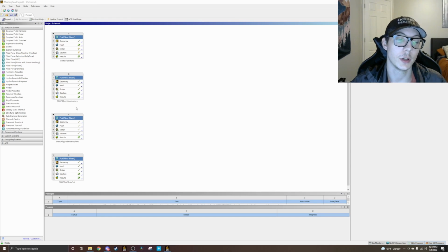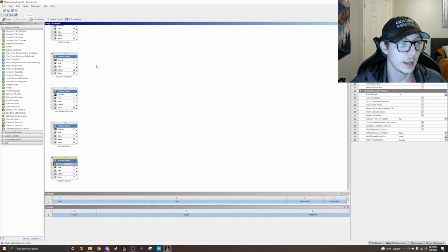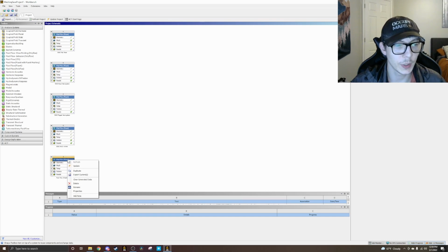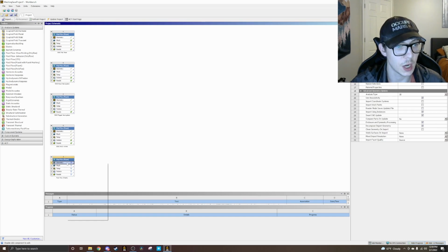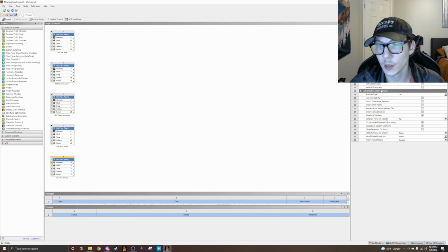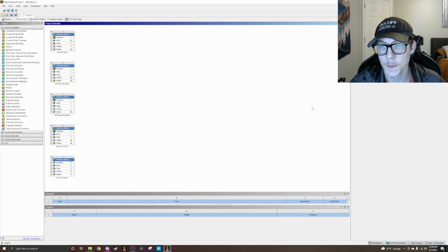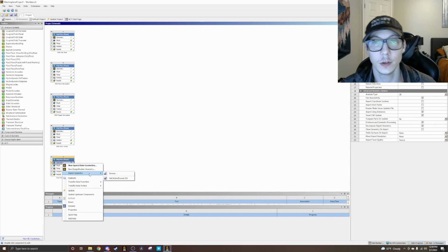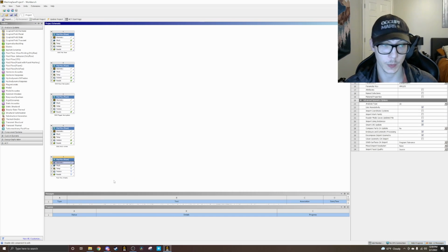We're going to open up Fluid Flow Fluent, a new one of those. Here it is. We're going to take this one right here and go into properties on the geometry, and select a 2D analysis because that's how we want everything to be going through. We're not doing 3D yet. I don't think we're going to end up doing 3D in this class. I might do it for fun, but we'll see. NACA windtunnel.igs is the file that we want to import. We're going to import it. Ansys took it beautifully. And there we go.